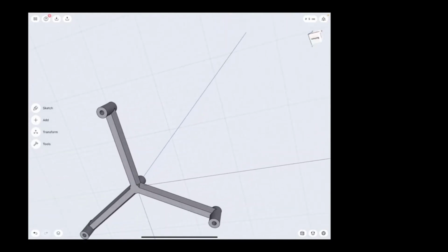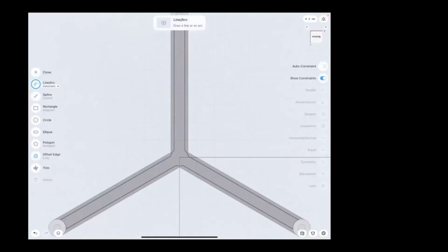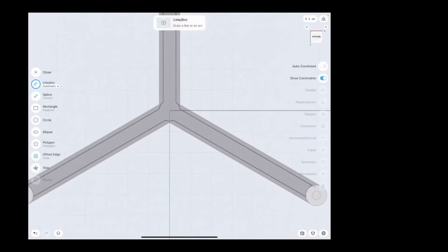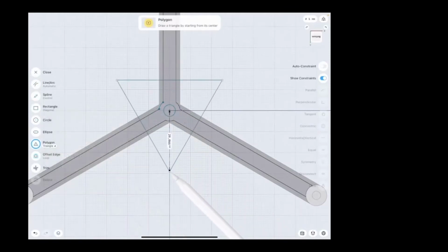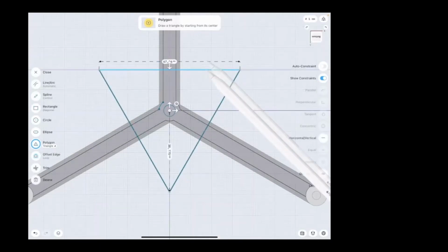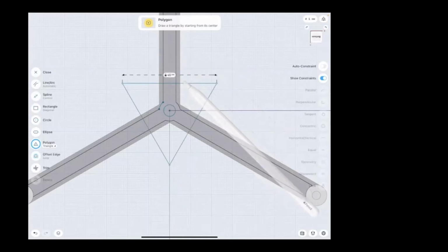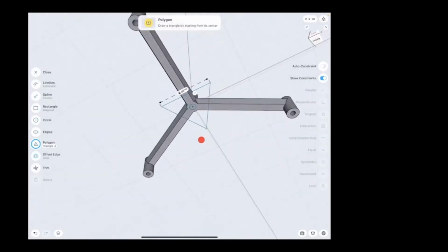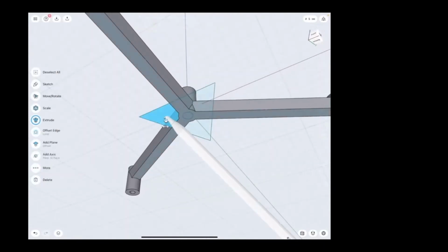lacks some mounting points. So I'm gonna do that next on the bottom face of this gripper. I will need one more reference, which will be a circle that is concentric to one arc of the edges. And I will create a second rectangle in my workspace. After defining and constraining this rectangle to be 45 millimeter long and horizontal, I can extrude it upwards.